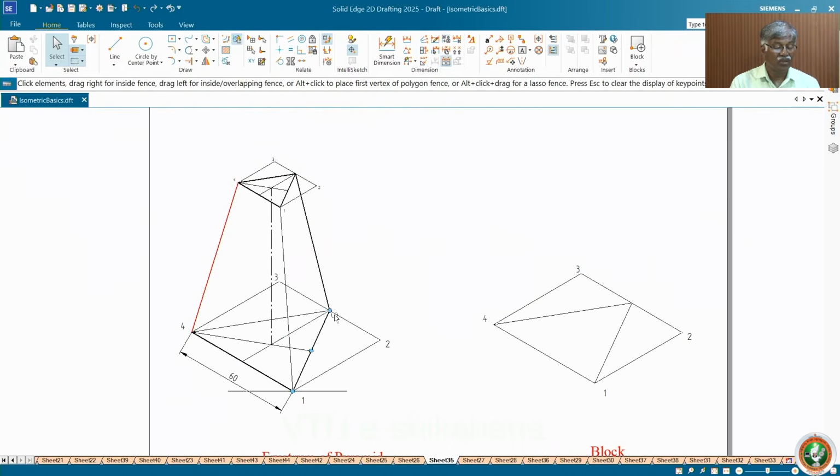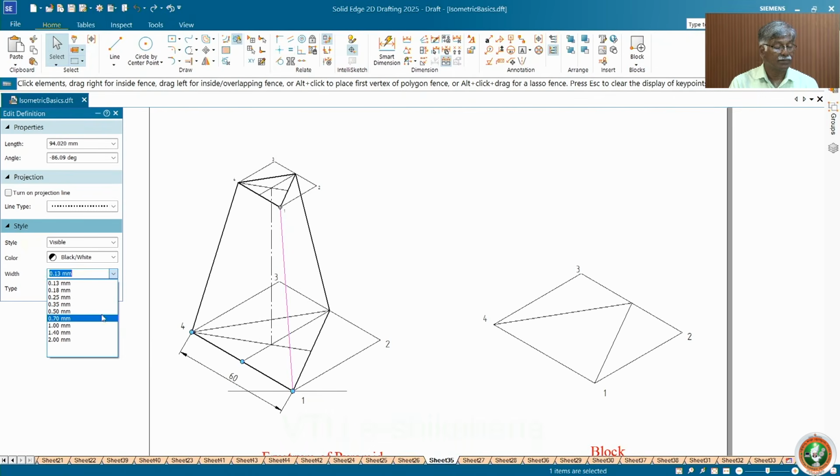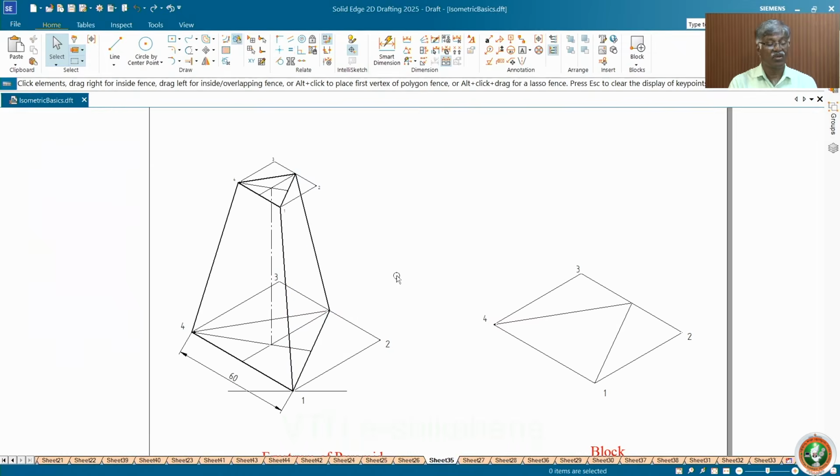What about this one, that is CA in this case, A, B, C, CA. It is not visible because it is on the invisible surface, other than the boundary line. Now what about AA1? AA1 is visible because it is crossing the invisible surface. Okay, so select this and make it dark. Yes, that's all. So we have created prism,